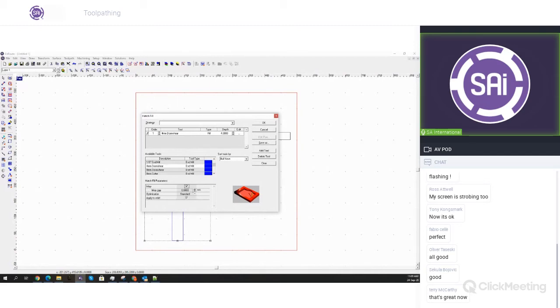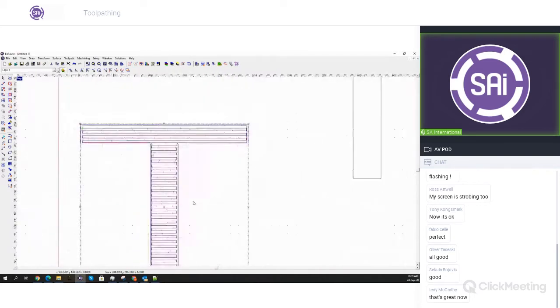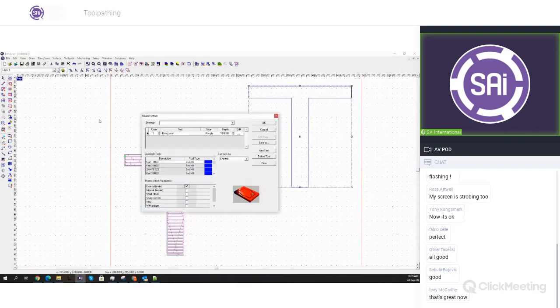And here we'll pick inlay, and we'll choose our inlay gap, which is going to be the complete gap between the pocket and the inlay. And then here we'll confirm this. And for the letter we're going to route out, we'll cut to a depth of 10, but we'll also use that same tool. So you always have to use the same tool to cut the pocket as well as the inlaid piece. Here we'll say inlay and put that gap of 1 millimeter.